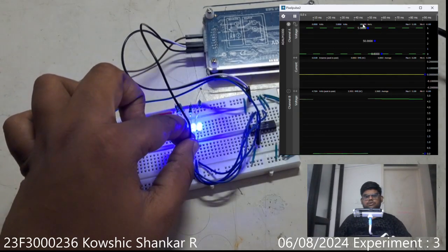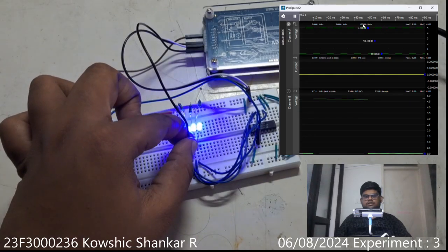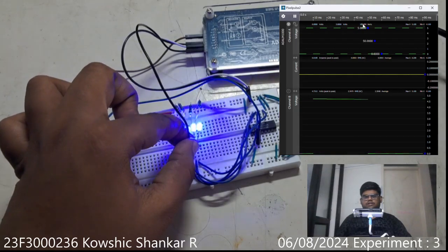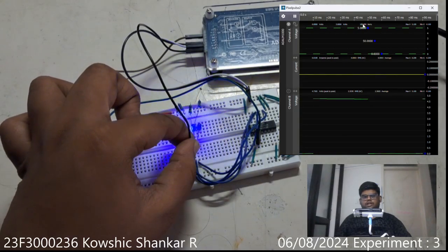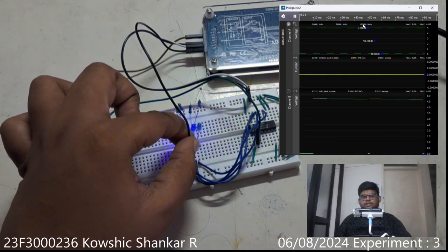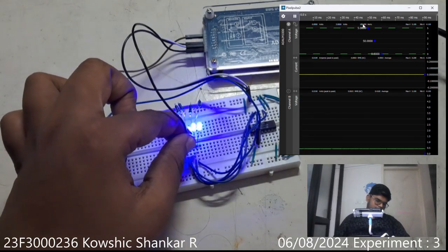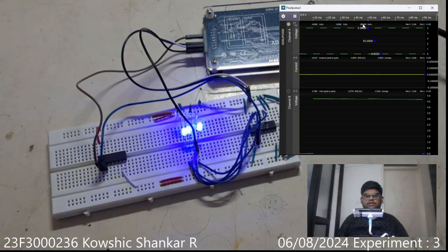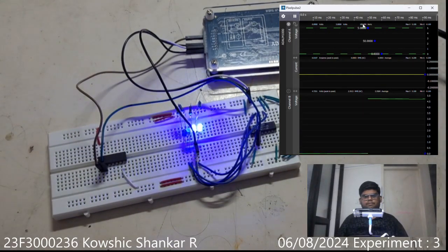This is the output of Q3. You can observe that the width of the pulse is slightly larger, as the third bit will not turn high as frequently as the first and second bits. This is the output of Q4, which will turn on much slower in frequency than the other pins.